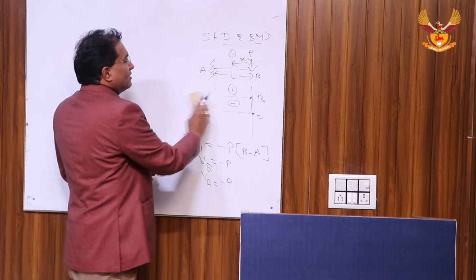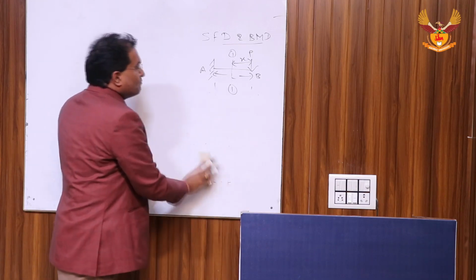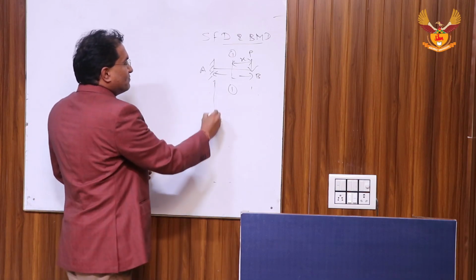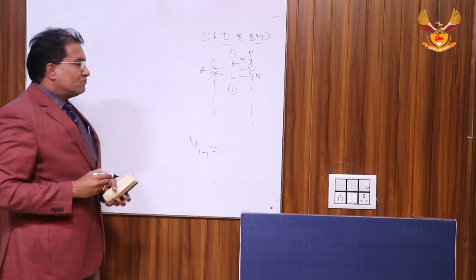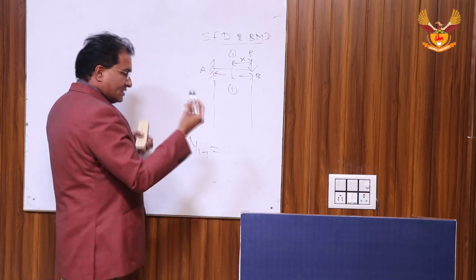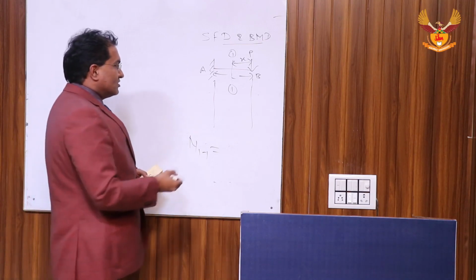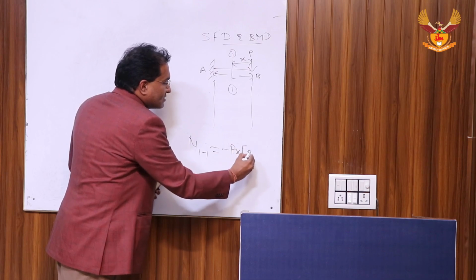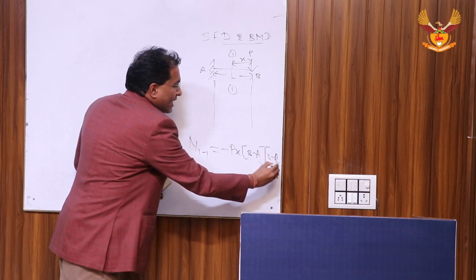Now let us see with the same section how we can plot bending moment diagram. Bending moment is nothing but force into distance. So M11, which represents the equation for bending moment, so this is clockwise, section right, I am considering negative. You can consider positive also, it will not make any difference in the solution. So moment is minus P into x,